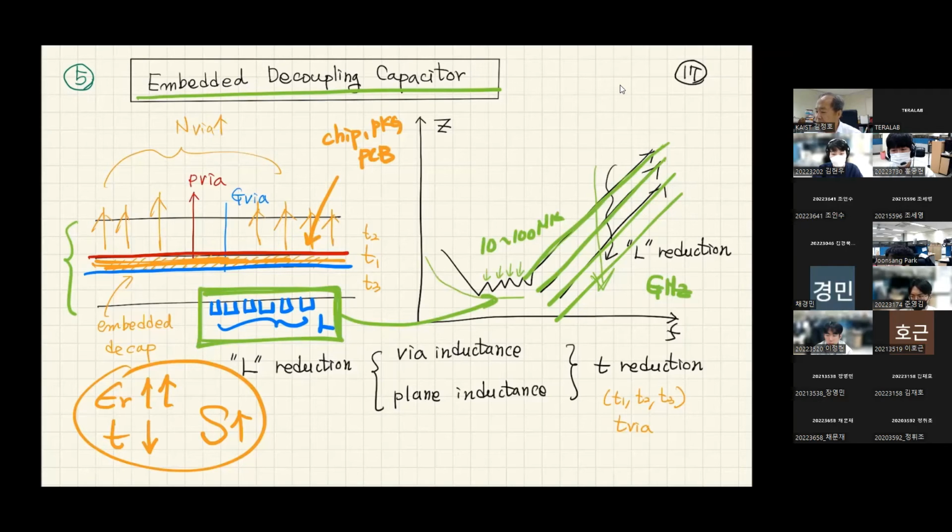So an ideal approach might be that we are putting some capacitance and we are broadening the mid-range frequency impedance by having multiple decoupling capacitor design, and eventually we have to reduce it by a certain amount.